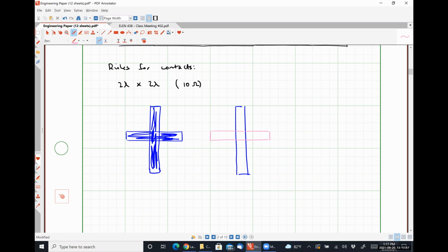This pink run is now physically separated from the blue metal run by a reasonably thick layer of insulation. Okay. All right. So having multiple metal layers really helps us out with routing signals around chips. If you're getting to the order of making your own microprocessor chip, 10 to 15 metal layers is not unreasonable. Okay.